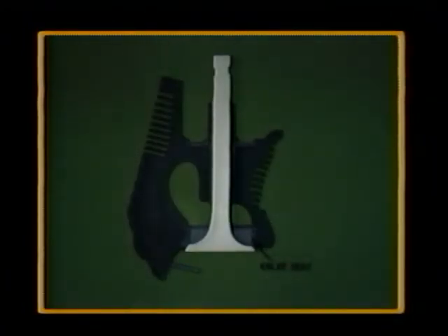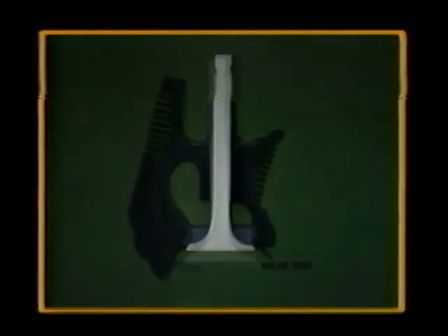The pounding action of the valves and the flow of hot gases would soon wear away the soft cast aluminum of the cylinder head, so steel or bronze valve seats are shrunk into place. Either bronze or cast iron valve guides hold the valve stem in place. This provides a bearing surface, allowing them to slide back and forth.